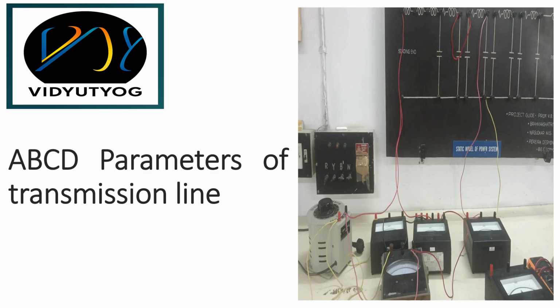So resistance and inductance, these are the parameters of the transmission line, as well as capacitance is also one parameter of the transmission line. Resistance and inductance make the series impedance, and capacitance and conductance make the shunt admittance of the transmission line. Shunt conductance is usually neglected in power transmission line according to the length when calculating the voltage and current.